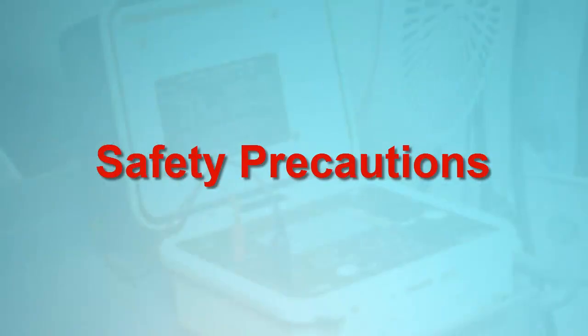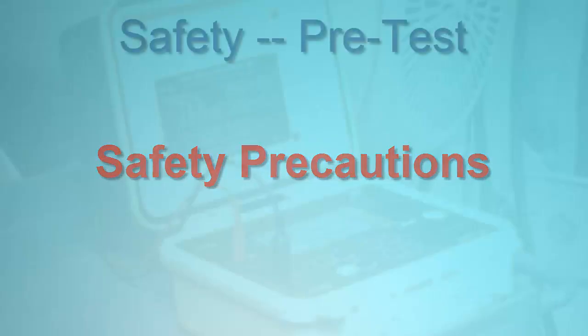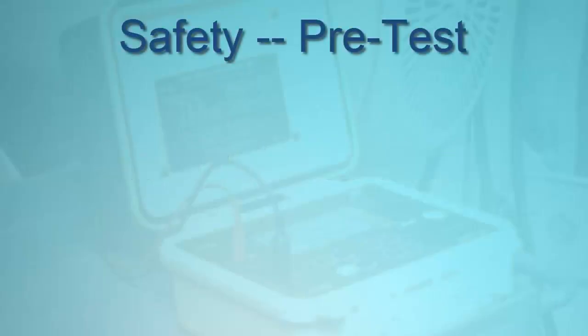Before performing any insulation resistance test, be sure to observe the following safety measures, as well as any additional instructions that come with your test instrument. Insulation resistance testing involves the application of high DC voltages. Therefore, properly preparing the system under test and the instrument used to conduct the test is crucial to your safety and helps prevent damage to your wiring and machinery.